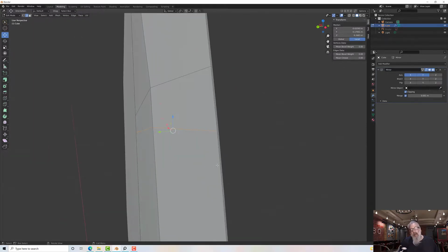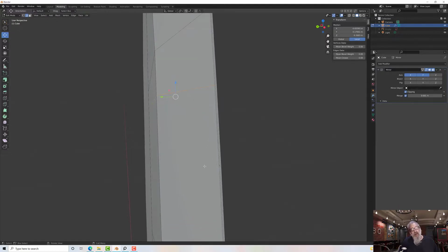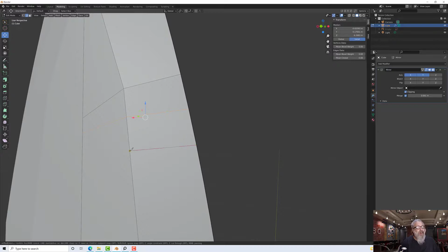And then I'm going to zoom in and find the next one. A little bit fiddly this, I could have done this a better way, I do apologise. So let's cut. Would help if my monitor wasn't so dusty, I wouldn't be mistaking dust for edges. So I've got one down there and we use K. So I'll click on this end, click over to my blade sort of ridge and then into the middle and then enter.